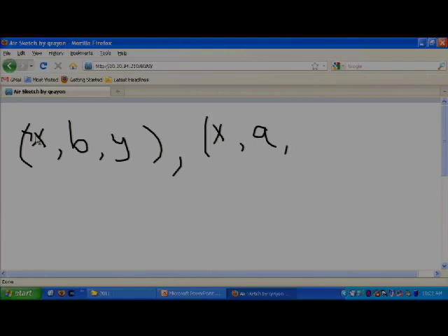So you'd end up in state B at that point, and then the next time you make a transition out of state B, let's say again you don't get an X, you will ultimately output a Y. So in this trace, even though originally you didn't get an X, at some future point, just because of the way the state machine is constructed, the only transition that you can make from an A will have to be on an X. So this X has to be followed by a Y in the future, and in fact it is.